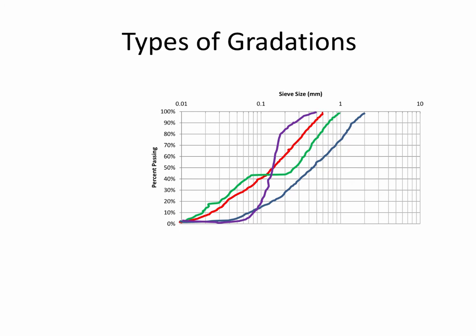And then after 0.12 millimeters, we're pretty evenly distributed. But in the range in between, we hardly have any soil aggregate pieces that are within the sizes in between. And so we get a flat line on our percent passing, and that's the gap. And that's why I said our sample is slightly gap graded.